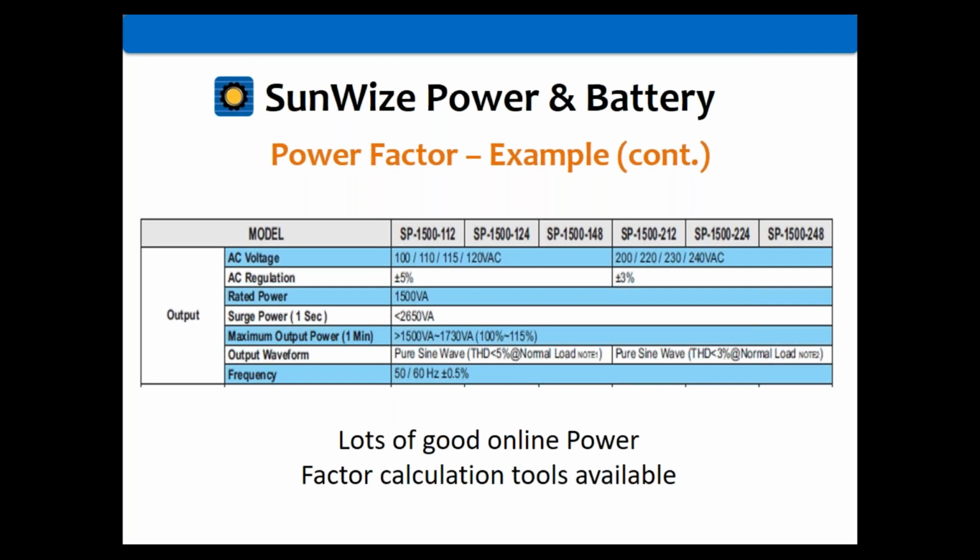The other time I see is with some of these LED power supplies. Although your LED lights may be drawing a small amount of power, you might think they only have a 12 watt LED. The problem is these power supplies, these ballasts for them, can be pretty bad actually, and they cause power factor issues. If it's as bad as 0.2, all of a sudden that 12 watt load is really consuming 60 volt amps. That's an inefficiency as well that causes an issue.